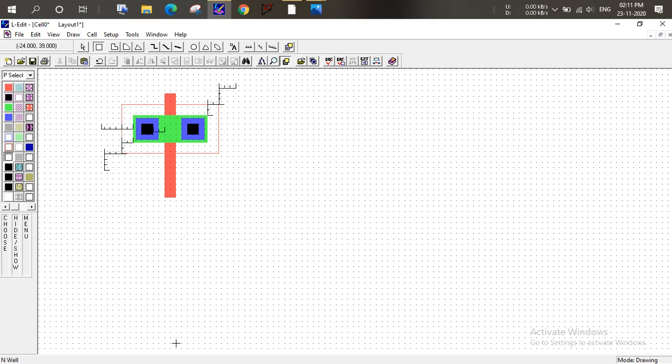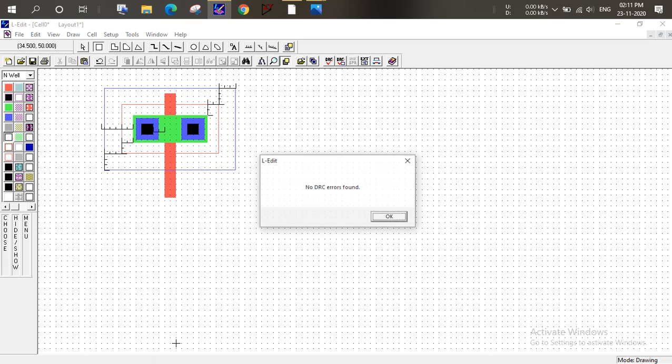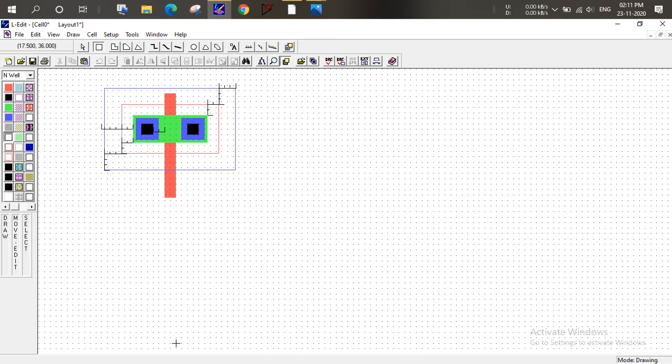Now we choose the N well for this CMOS. Okay, that is the CMOS. Now check the DRC error. No DRC error. Okay, fine.